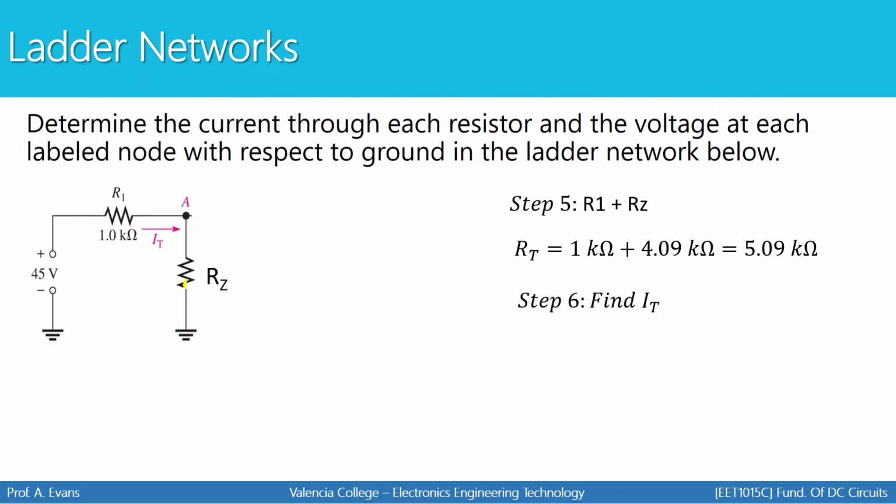That's the total resistance. So I've started from the right, worked my way to the left, collapsing two things at a time. They might be in series, they might be in parallel, but I've made one collapse and given it a new name, a new label. And as I have shown you a new picture with each step, you should also redraw your circuit with each step so that you can see how you collapsed it. And you may have to go back to one of those intermediate steps to find a value later on.